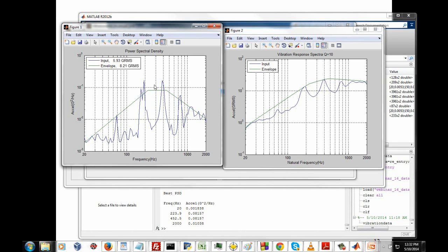What we've shown is that we can clip these peaks from the flight data. Now, throughout the industry, there are different rules of thumb. You might see that it's permissible to clip a peak by 3 dB, for example. And rather than just rely on those rules of thumb, why don't we use a VRS to guide us through that clipping process?